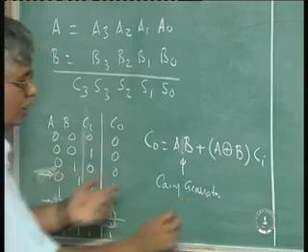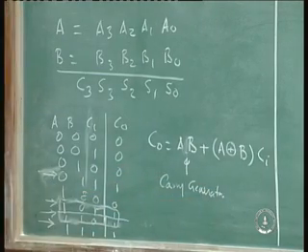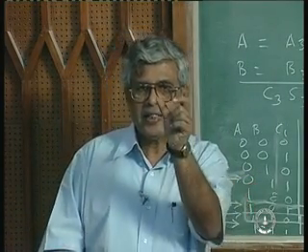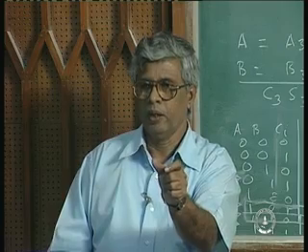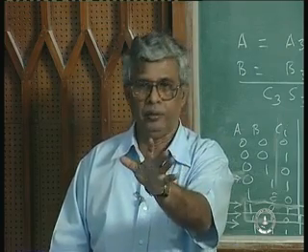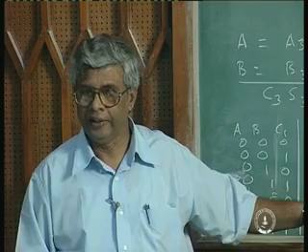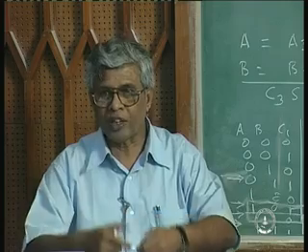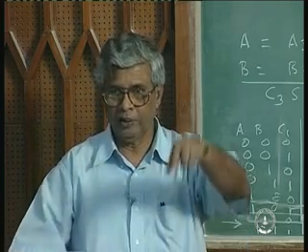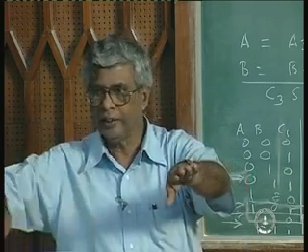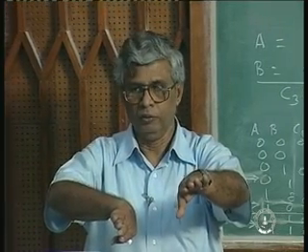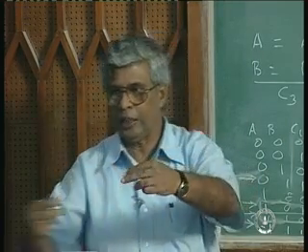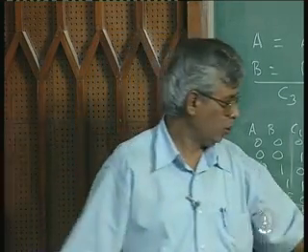in that stage, whatever the stage, we have multi-stage addition, 4-bit addition in this case, it could be 8-bit, 16 bits, or 32 bits. At each stage or each bit, the carry will be generated if the corresponding bits are both 1. That is why it is called carry generate, irrespective of whether the previous carry was 1 or 0. A fresh carry is generated at that stage if both A and B happen to be 1 in that stage. You do not have to look at the carry pushed from the previous stage. The other condition is when A exclusive OR B of that stage is 1, the carry will be generated only when the previous carry was pushed into it. This one I will call carry propagate.